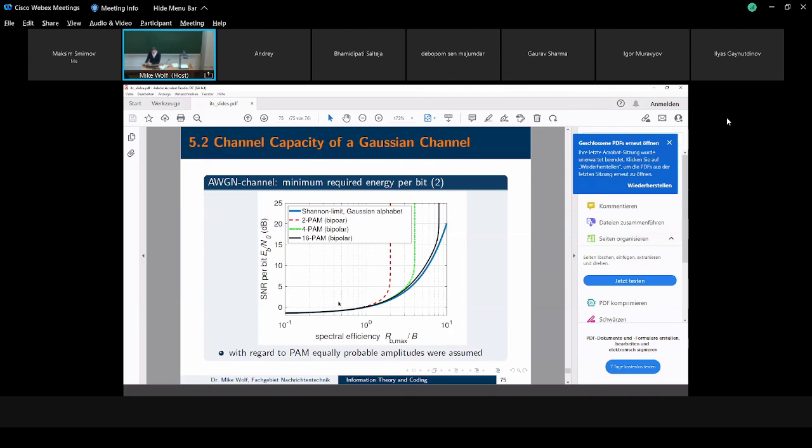But if you further increase the bit rate, you need more levels for transmission. For instance, if you use 16 equally distributed levels, not Gaussian, you can transmit 4 bits with each symbol in the best case, if you have low noise, and 4 times 2 means 8. And you see here is a gap between the Gaussian distribution, blue, and these equally distributed signal alphabets, which are real world in most cases. And there are even approaches to close this gap, and this is called signal shaping.